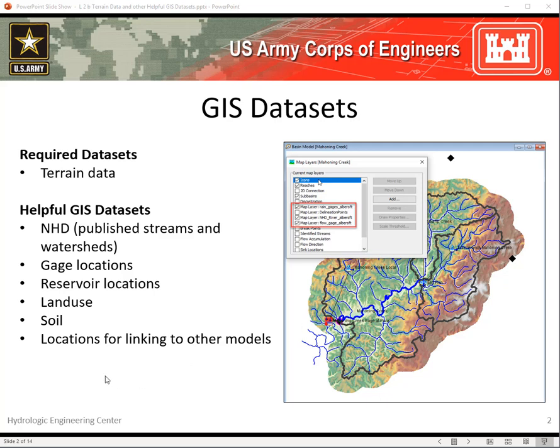location. If you have reservoirs, then you could load those reservoirs as polygons and display them within the basin model map. If you have land use information, soil information, you could load those as ASCII files, display that information in the map, or as the other videos are going to show, you could use that information to estimate your basin model parameters, or specifically the subbasin loss parameters.